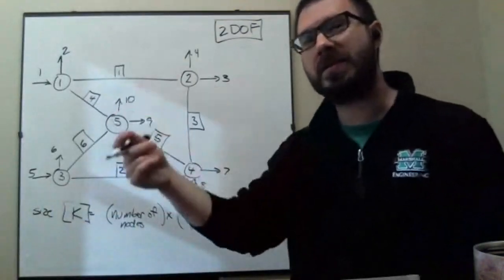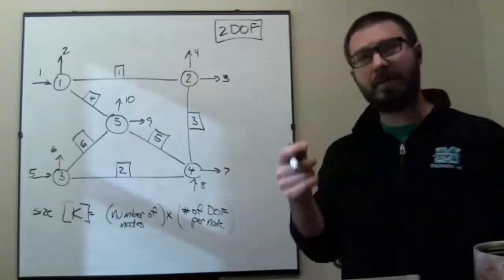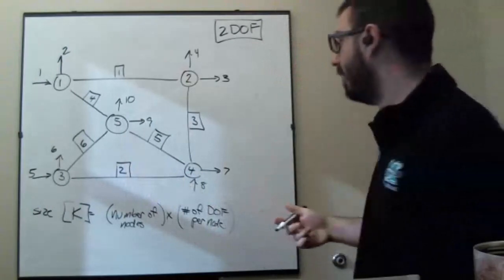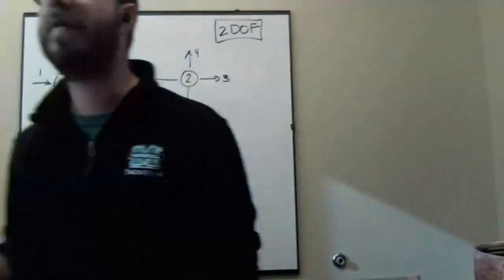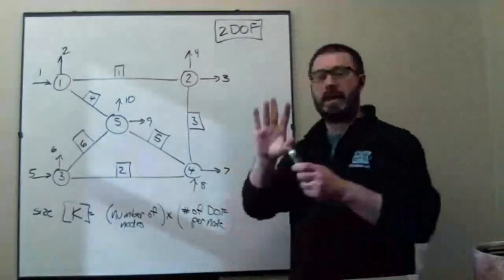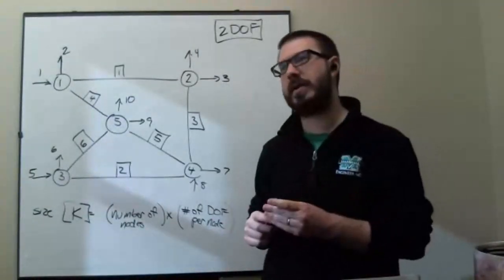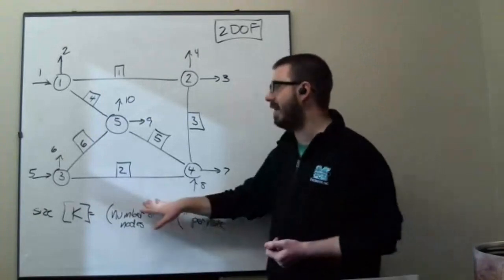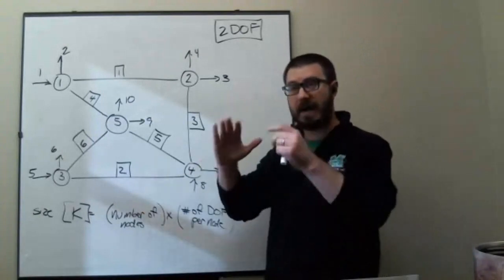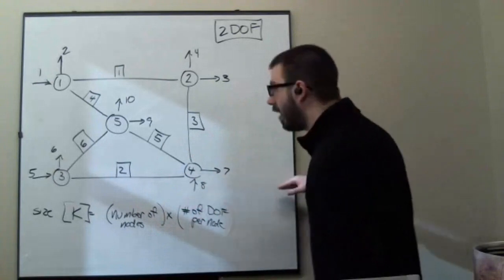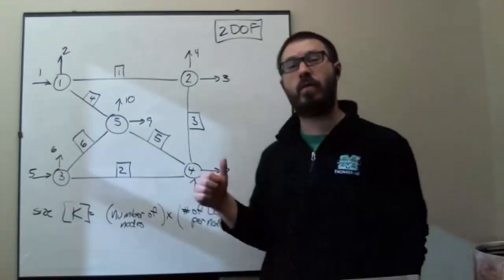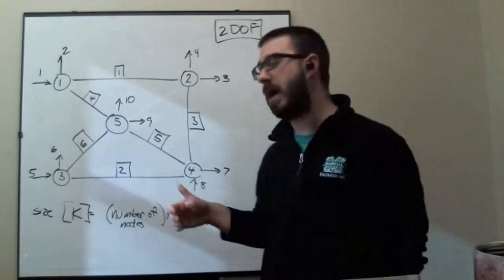All right. So that's the first thing to keep in mind. The other thing to keep in mind are your member codes, right? So like, for instance, are they always in the same direction? Okay. So when we're talking about degrees of freedom, what I'm indicating here are the positive directions, right? Remember, we always consider forces and displacements to the right are positive, and forces and displacements that are upward are positive.